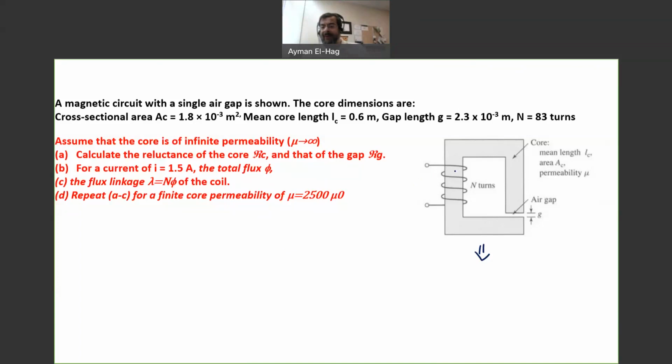In this one, we have one source of magnetic field, or one source of MMF. So this will be your MMF. Now this will be producing the flux. How? When the current goes into the coil, your four fingers will be in the direction of the current, and this will be the direction of the flux. So you'll have the flux going in this direction. As you can see here, the flux will be going all the way until it comes back. So we have only one loop in the magnetic circuit, so we will have only one loop in the electrical equivalent circuit.